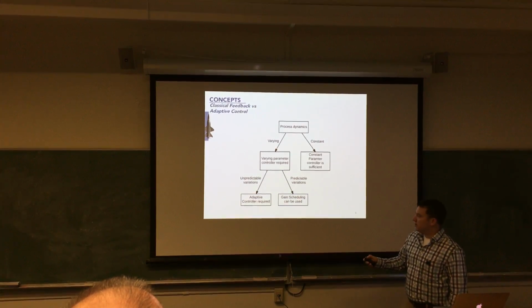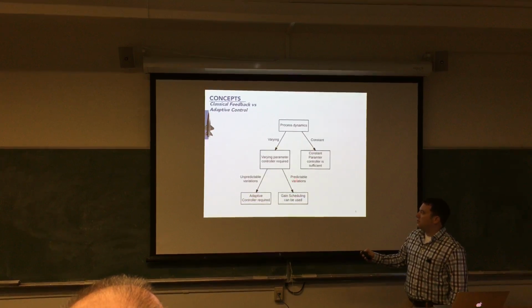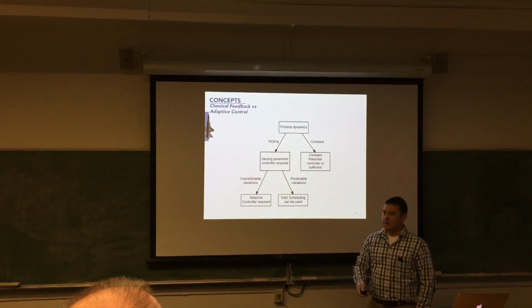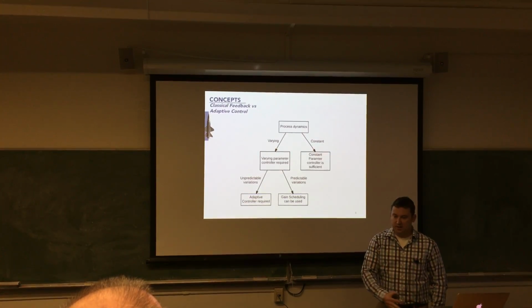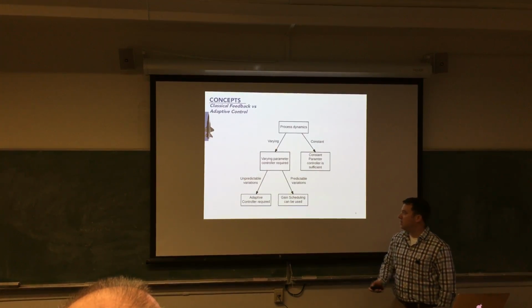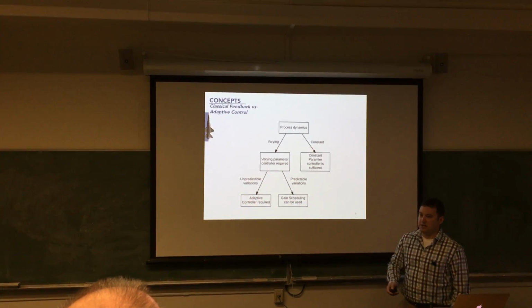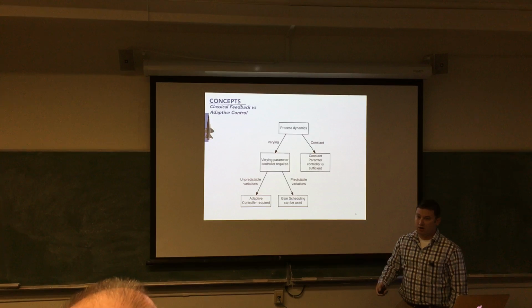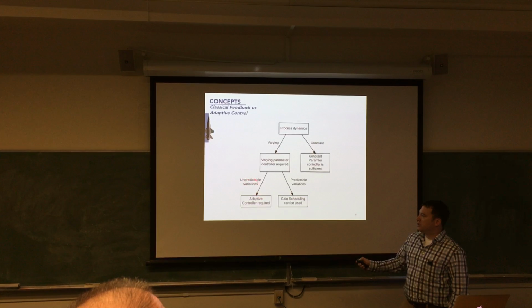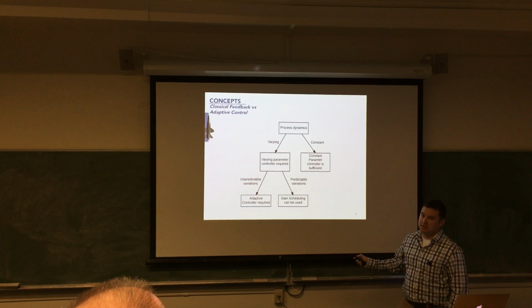The conventional way it's done is with gain scheduling, because these variations are predictable. So when you drop a JDAM and the speed is increasing as it approaches the ground, those are all points that you can gain schedule in your conventional controller. The problem with that is it's very costly, which I'll discuss. And then lastly, adaptive control really shines when there's unpredictable variations, like battle damage or actuator hardovers and those kinds of things. So what I really wanted to do was push some of these benefits of adaptive control into these predictable variations as cost savings.